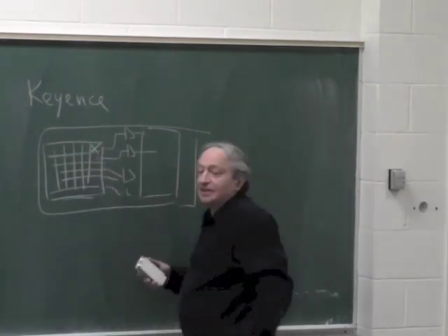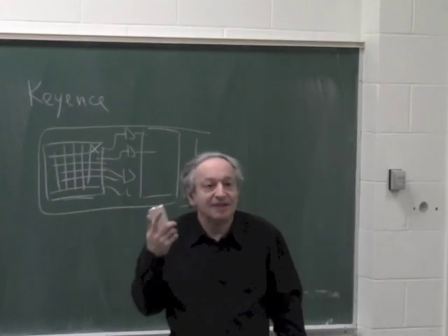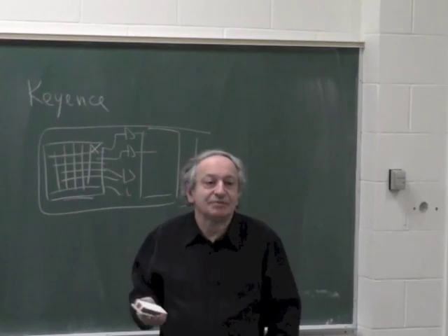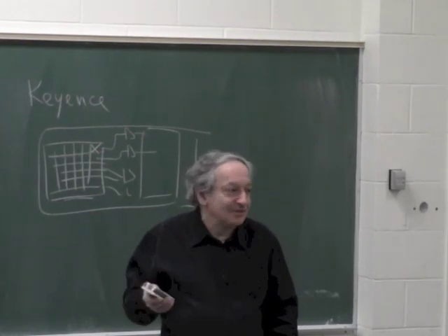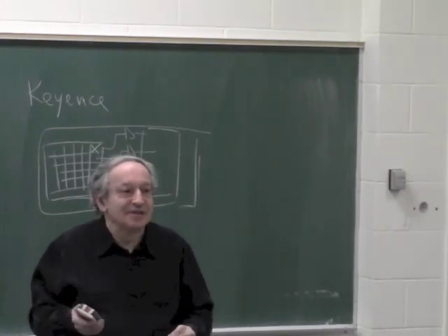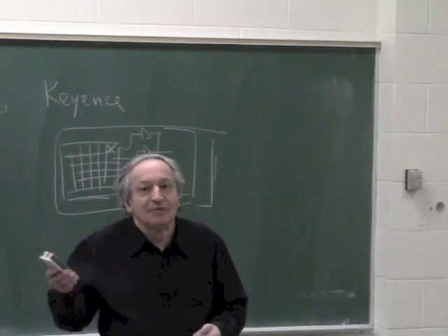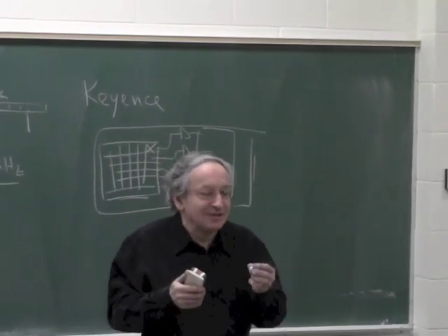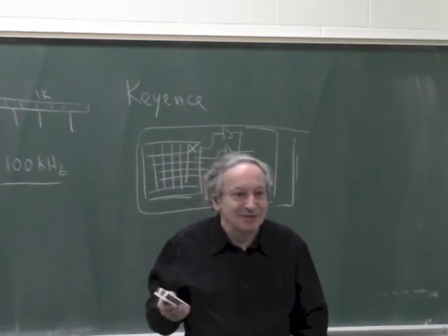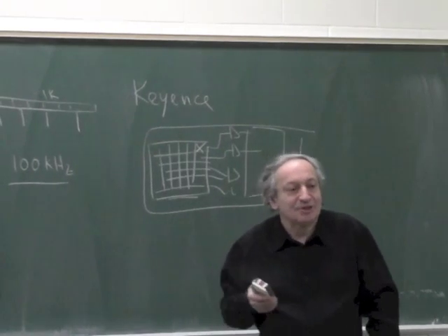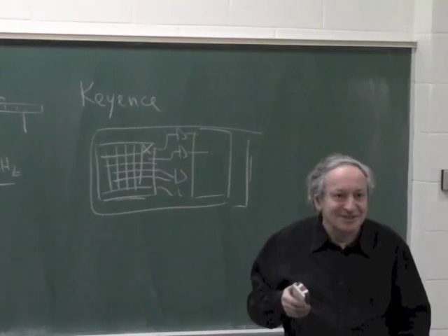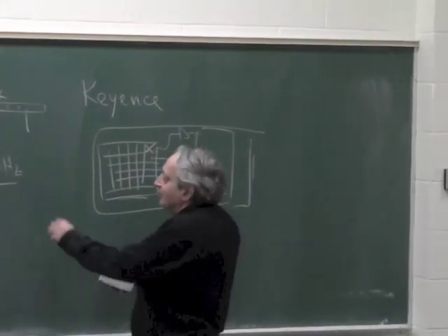And then you start asking the question, how fast can a single detector be? So a normal silicon detector, if you don't do any tricks, is 1 megahertz. If you start doing some tricks, like a pin detector, you can go to a gigahertz. How do I know that? Look at fiber optics. In all of fiber optics, the detector goes to many gigahertz. So there's really no limit if you're making a custom chip. You can go to specialty materials, gallium arsenide, pin detectors, and get many gigahertz. But as commercial chips, these are good numbers to keep in mind.